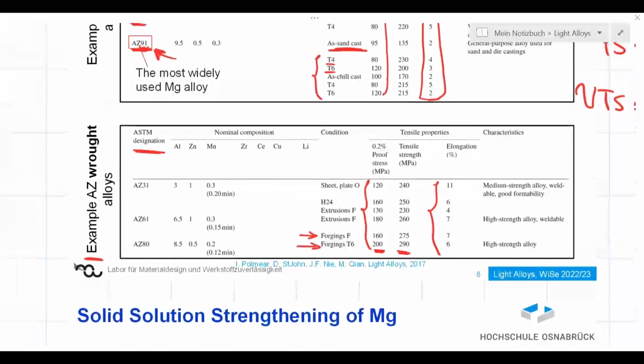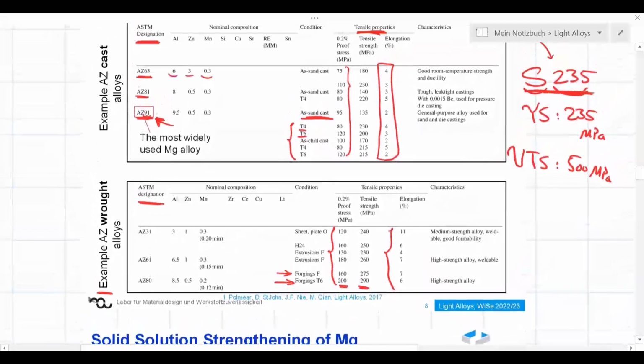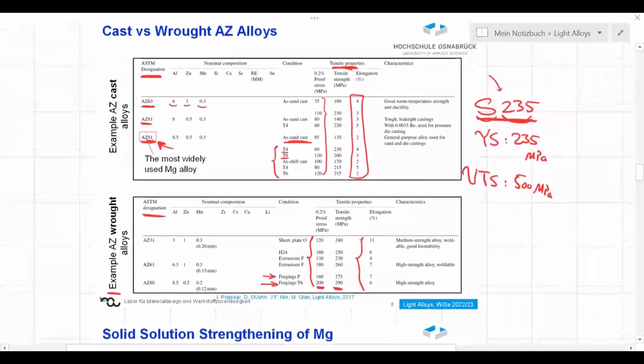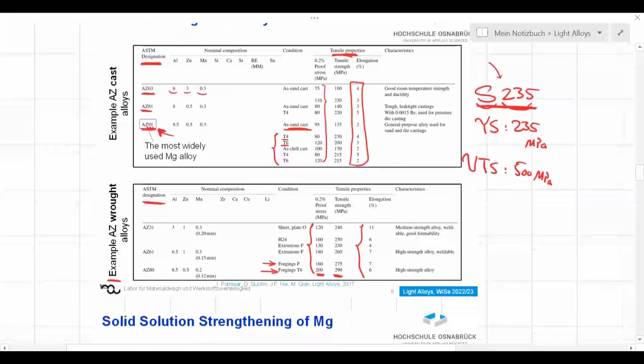But we also saw the problems of high pressure die casting. One of them was you have to produce a part in a very high quantity, because design of the die is going to be very expensive, right? Design of the tools and the dies. And we should also consider that those parts could have a high porosity. Maybe they are leaking kind of alloys. They're transparent to gases, right? And these are some of the issues to keep in mind if aiming for die cast magnesium parts.